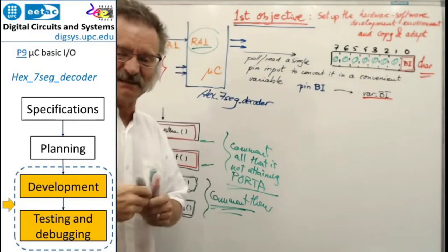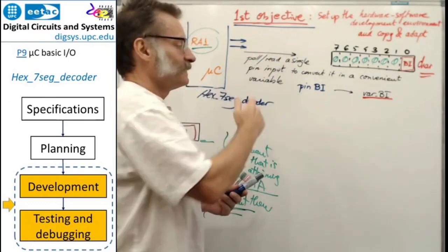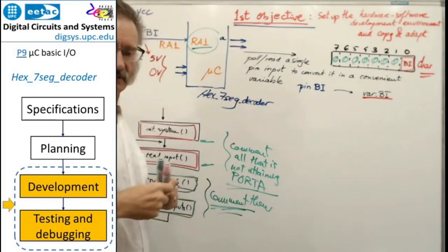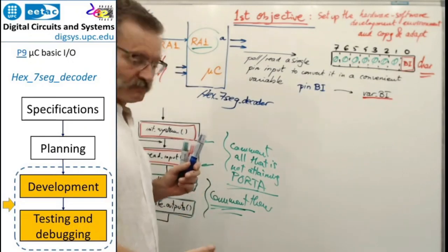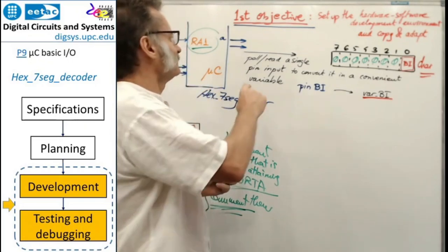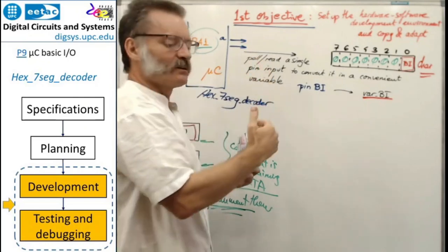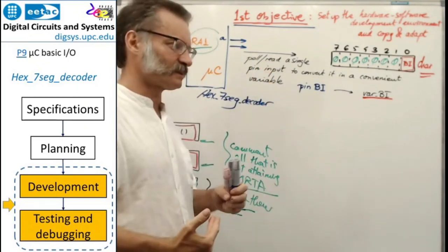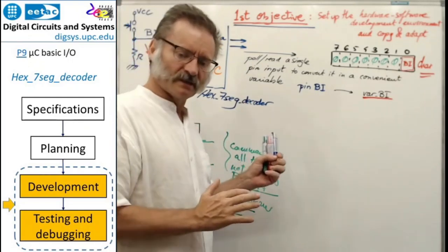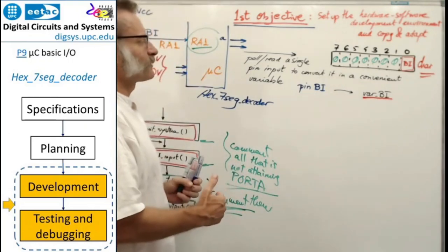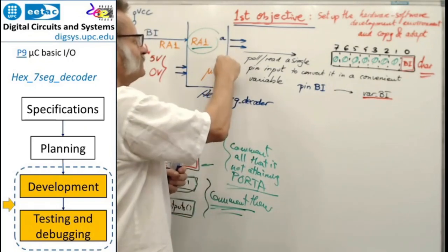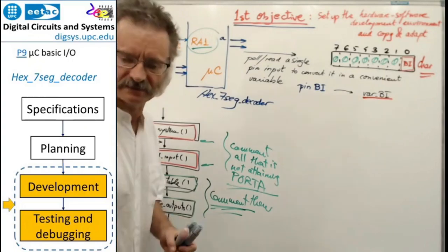And again, if it's the first time that you will go writing, your purpose is to write a single pin, for example, the output A. That's enough. Writing the A, and testing that these ones and zeros in A have been converted into light, no light, in a 7-segment display, for example a common cathode display. That is going to be enough, so that later it's not going to be a problem to recopy and readapt it and learn the lesson to write other ones, B, C, D, and so on. So that is the initial idea.